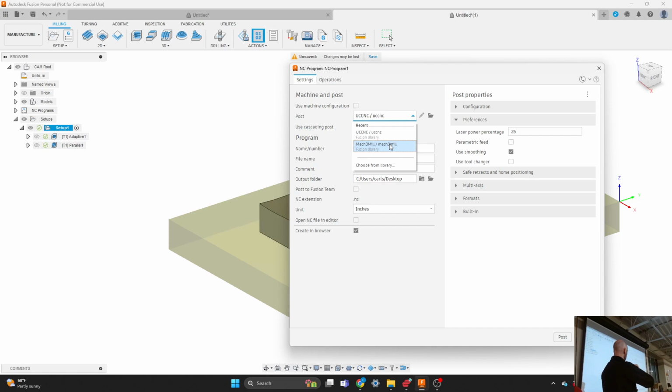How did you bring that pull down? Where it says post-process? Yeah. I said choose from library. You might have to go and say choose from library, and then at that point it'll, yeah, and then there, oh yeah, local, there you go. Go back to choose from library. Click on cloud. Or Fusion library. There we go, there they all are.